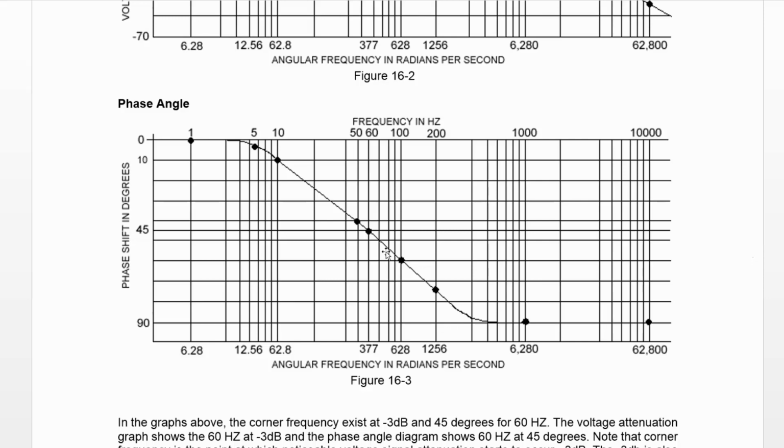The main thing we want to say is that proportional band has an offset. It doesn't correct. It only stops the upset of the disturbance. Watch the video on tuning, which is video 7M, Ziegler-Nichols tuning, and you'll get more of an idea of what proportional is and how it responds and how it never corrects back to zero, your set point. It always has an offset.